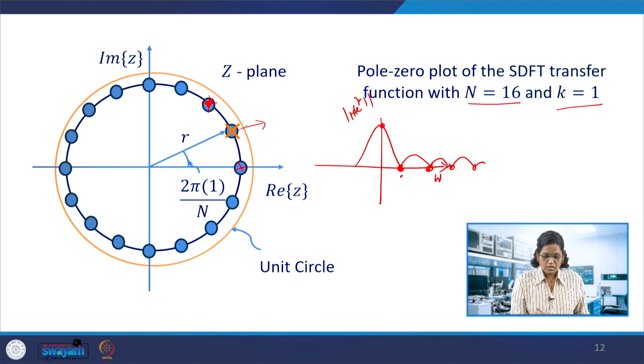So that will be marginally stable, and a slight change in the noise or anything, that accumulation of the error, virulent effects and all those things would push the pole outside the unit circle. So this system will become unstable. Instead of giving the fundamental signal, the instantaneous signal, it won't stabilize; it would start growing if it is slightly pushed away from the unit circle.